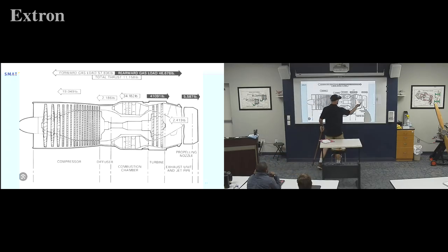And then the last part, our nozzle, that one's trying to go backwards. It's like, what in the world is going on here? Well, basically, these shoulders here, where we narrow down our gas and reaccelerate it coming out the back, it kind of makes sense that you got all the pressure coming out, and they're holding it in. So they would try to go. So all that to say, those are the sections of your engine and the overall direction that each section would want to go.